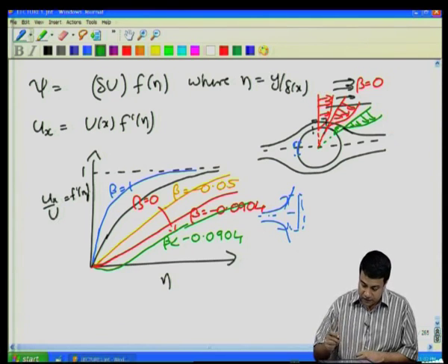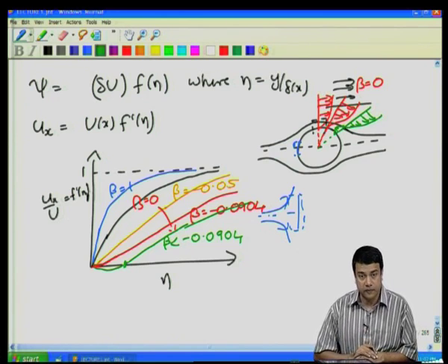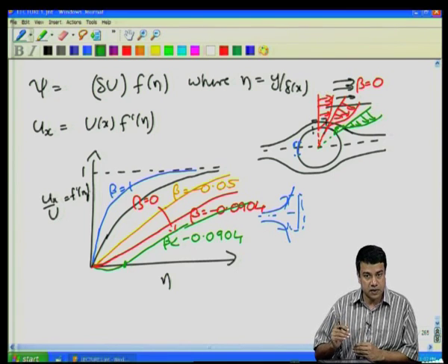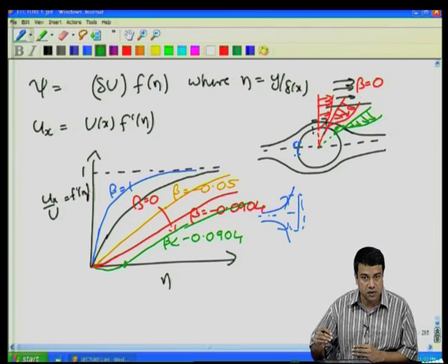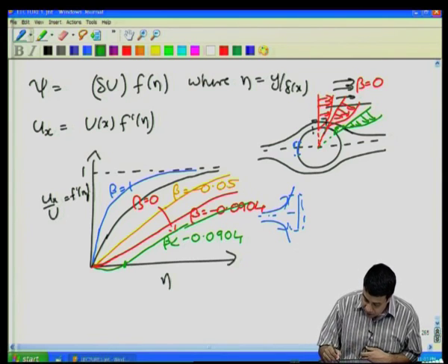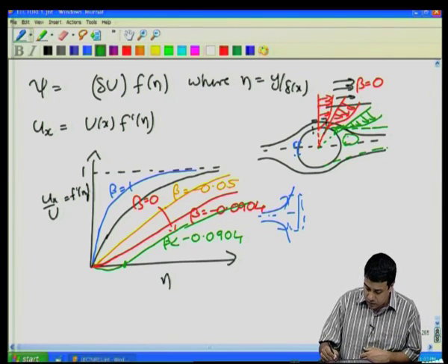So, you have a second point here, corresponding to this point here, at which the velocity is equal to 0. So, you have 2 points at which no slip is satisfied. That means that the second point also acts something like a surface with a zero velocity condition. The tangential velocity comes to 0 at this point. The normal velocity of course is equal to 0 because it is perpendicular to the streamlines. And this region behind is what forms the wake. And you have recirculation within the wake.